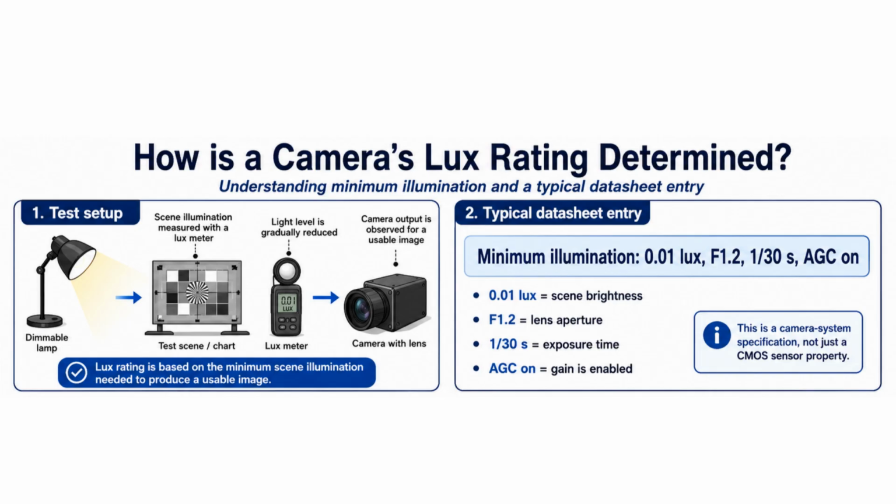Here, 0.01 lux is the scene illumination. f1.2 is the lens aperture, 1/32nd is the exposure time, and AGC on means electronic gain was enabled. AGC stands for Automatic Gain Control. In a camera, AGC automatically increases the electronic amplification of the sensor signal when the scene becomes dark. Therefore, the lux rating describes the complete camera system under stated test conditions.